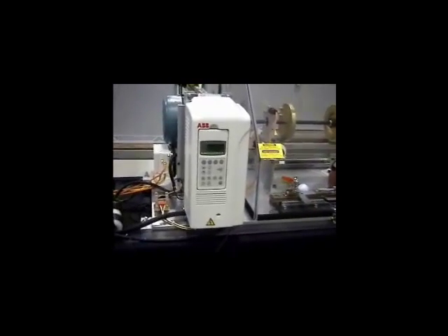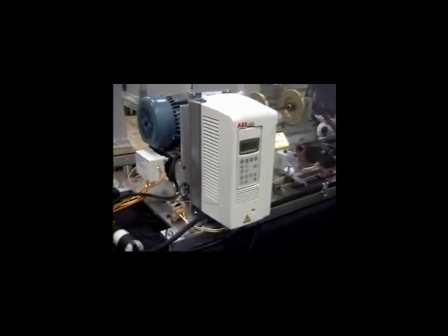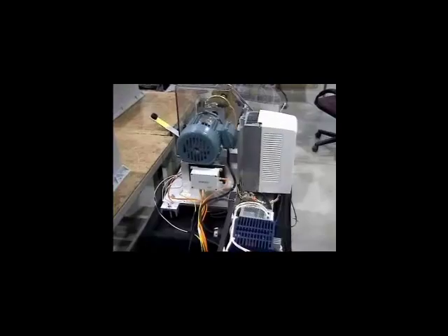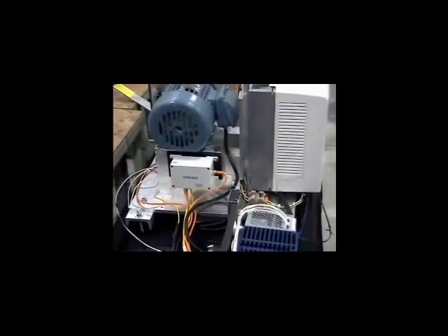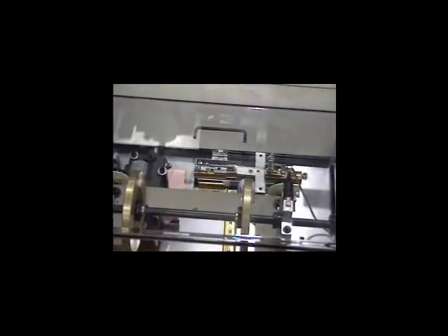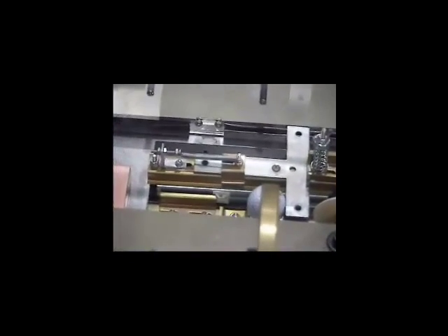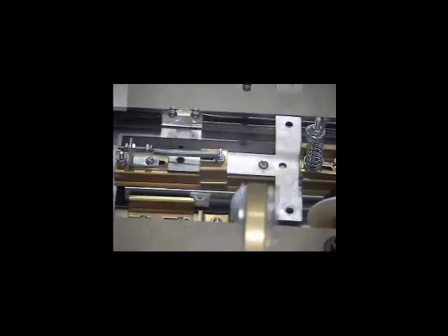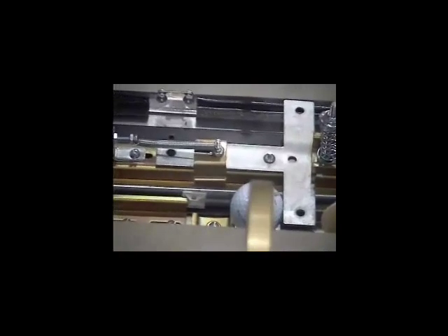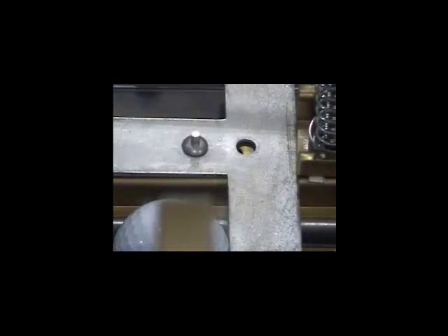A variable frequency motor drive causes the motor to vary its speed over the life cycle of the physical asset. An unbalanced rotor induces vibrations over the entire structure, especially to the failure mechanism, which is that T component held in place by friction and spring force. When the frictional resistance to failure falls below the applied load, failure will occur.